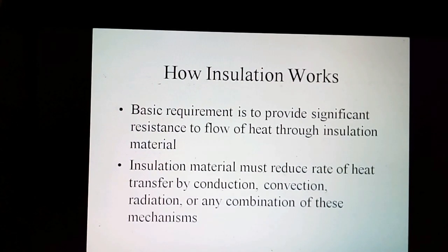How insulation works. The basic requirement for thermal insulation is to provide a significant resistance path to the flow of heat through the insulation material. To accomplish this, the insulation material must reduce the rate of heat transfer by conduction, convection, radiation, or any combination of these mechanisms.